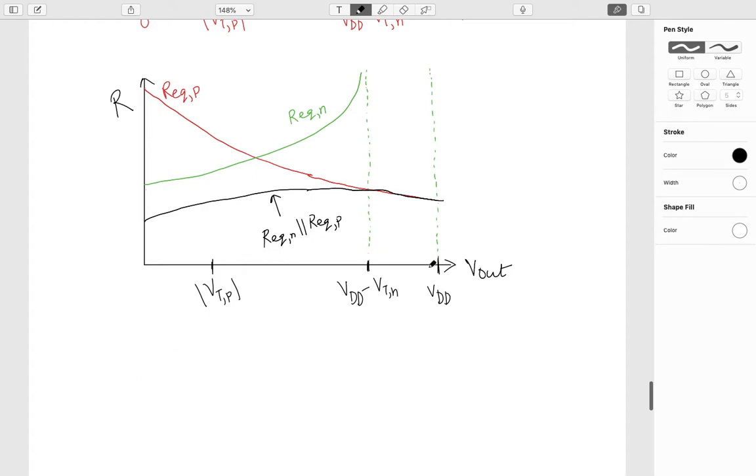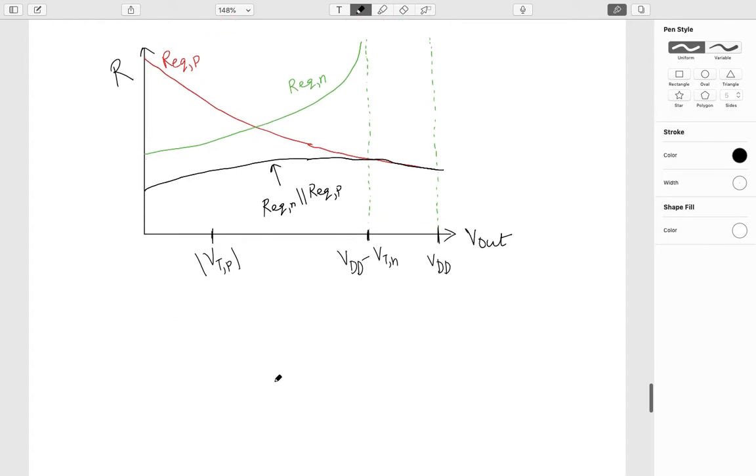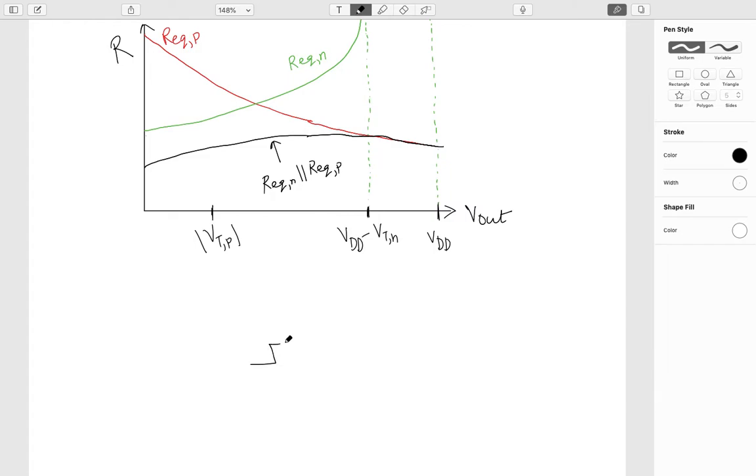So now let's come out. We have finally concluded that if I have an NMOS here, and I draw a PMOS here, something like this with a bubble up, PMOS, and the NMOS here with no bubble, this is the notation that is generally used for a transmission gate. So this is my V in, V out. Let this control voltage be called C, and this control voltage C bar.